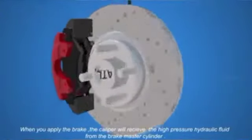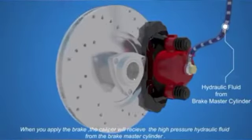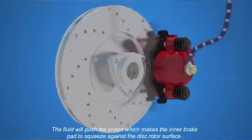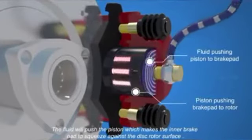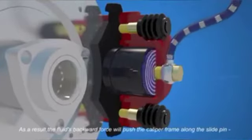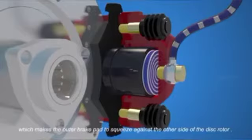When you apply the brake, the caliper will receive the high-pressure hydraulic fluid from the brake master cylinder. The fluid will push the piston, which makes the inner brake pad squeeze against the disc rotor surface. As a result, the fluid's backward force will push the caliper frame along the slide pin, which makes the outer brake pad squeeze against the other side of the disc rotor.